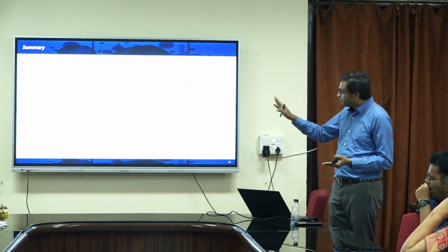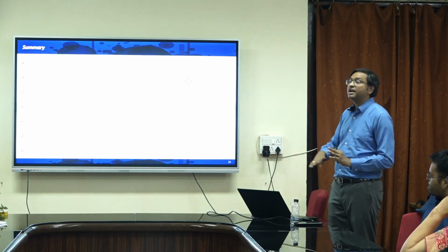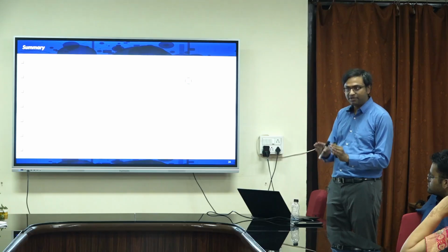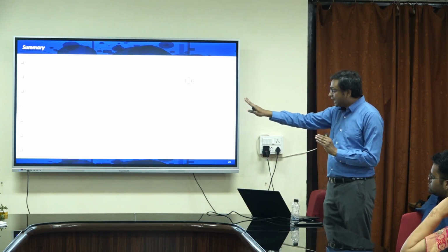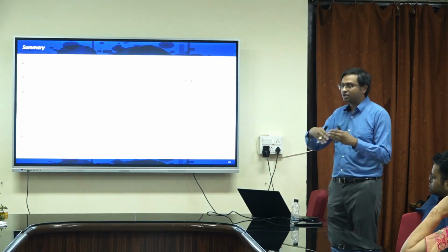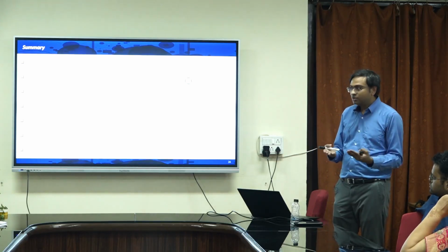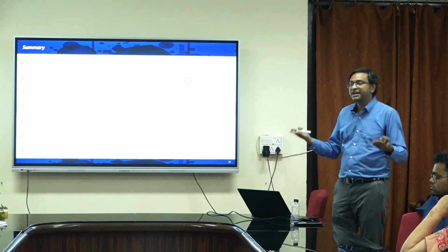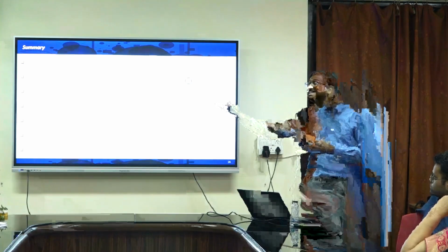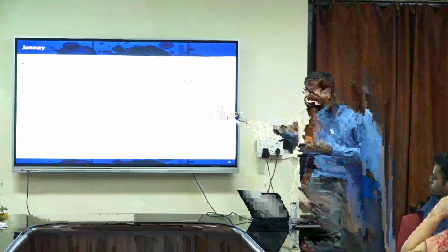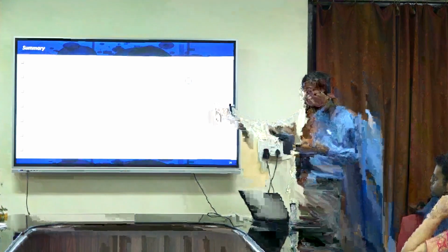Fourth, gold, bismuth, antimony appear to be promising because they give me low contact resistance for MoS2 or N type. And then we need degenerate doping underneath the contact, because we cannot get rid of the Schottky barrier, we have to thin it down. And in order to thin the Schottky barrier, I need degenerate doping, and this is an open field. Nobody has looked into that.